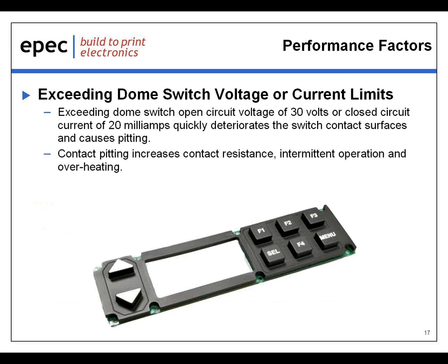Exceeding dome switch voltage or current limits. Dome switches operating in a circuit with open circuit voltages exceeding 30 volts or closed circuit current exceeding 20 milliamps will cause contact pitting very quickly. And contact pitting increases the contact resistance or intermittent operation and potentially can overheat.